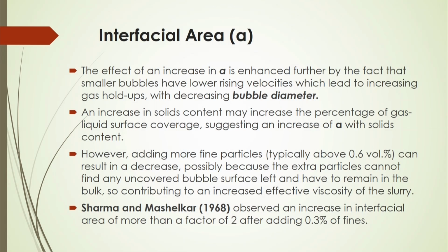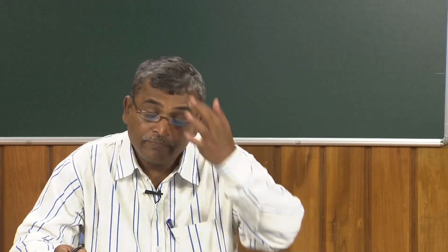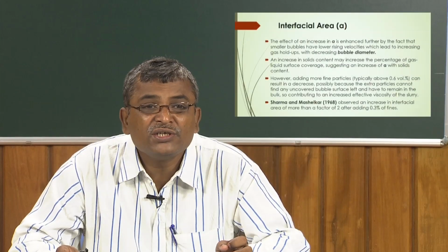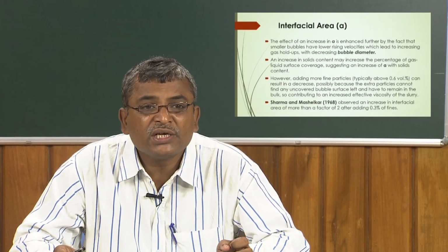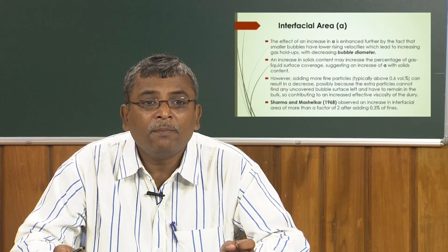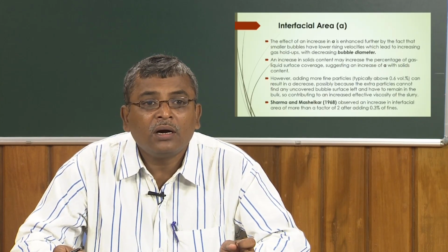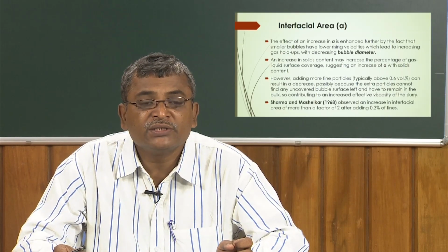Very interesting: this hold-up or bubble size depends on the physical properties of the system and also on the fluid flow inside the bed. Fluid flow changes the kinetic energy and the momentum exchange between the phases, because of which there will be breakup or coalescence of bubbles, and a net change of bubble size inside the bed.